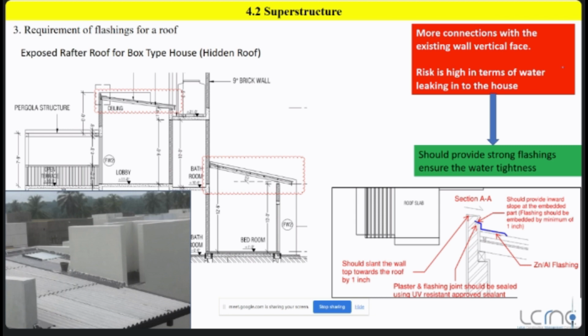Now this is the most important thing when it comes to roofing. There will be some water leakages if you do not properly provide the flashings to the roof. For example, let's say this is the wall. This wall is going down. This is actually the water tank slab. The water tank is not placed inside, but this is a water slab. Here, this is a water tank wall.